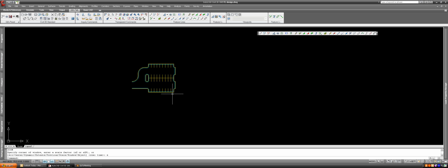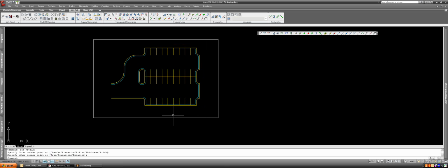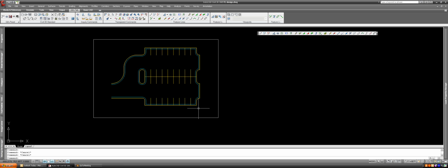All right, let's create a little parking lot. What we're going to do is go 2% down to the center of the parking lot, and flow along the center, or along the back of all of the parking spaces, down to a point here that is the lowest point in the surface. First, we make a rectangle around the entire site. Once you use the rectangle command, it makes a polyline. I'm going to create a feature line from that polyline so that we can start using it.